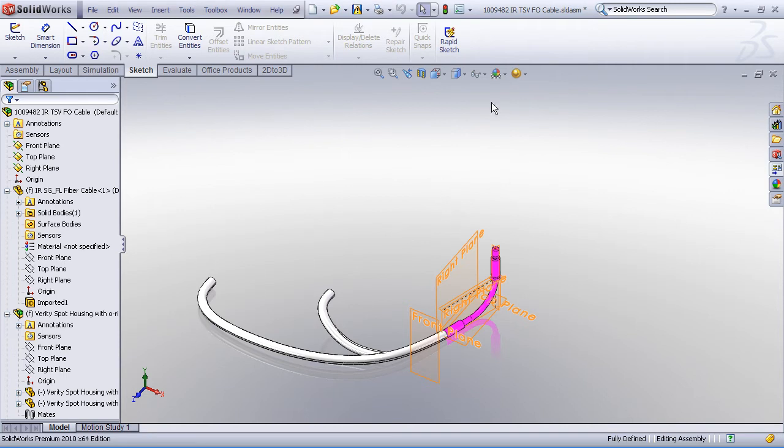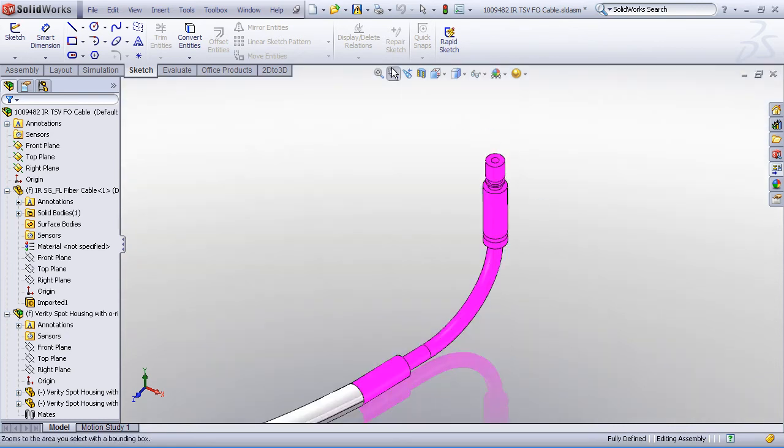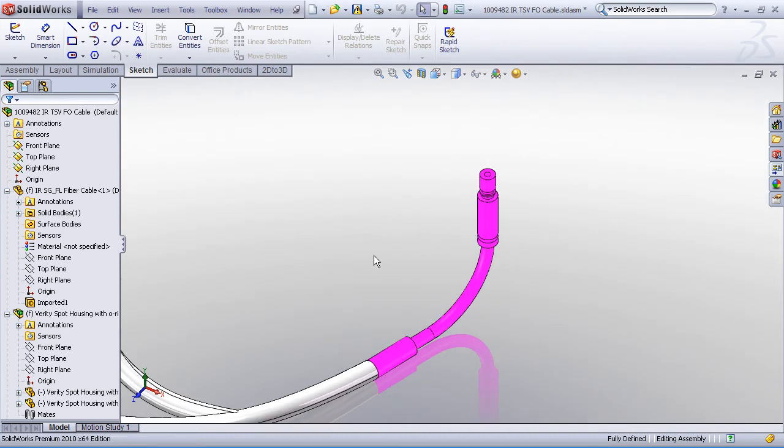So we've opened up your file in SolidWorks, and I'm going to hide the reference planes. What we need to do is create our own internal coordinate system, a reference coordinate system that will give a little bit more of an intelligent orientation of the axes. So to do this, since you don't really have any hard straight edges on the model, we're going to first need to draw ourselves a little sketch that will represent what we want the X, Y, or Z axes to be. Now let's do this as a 3D sketch.